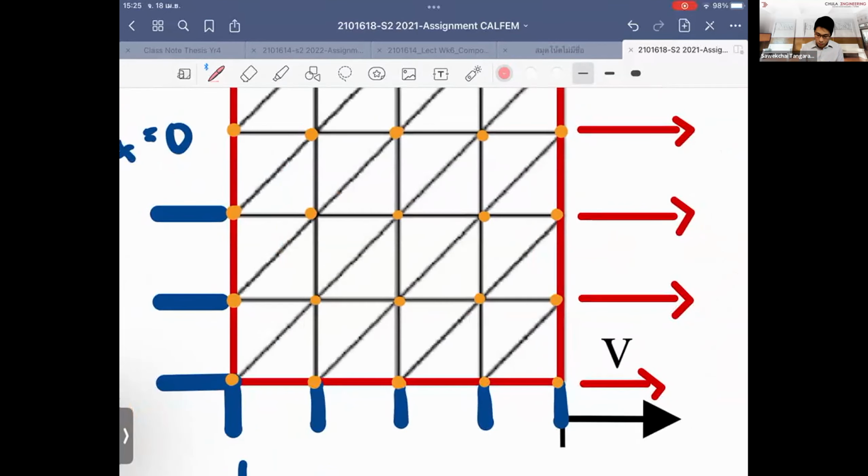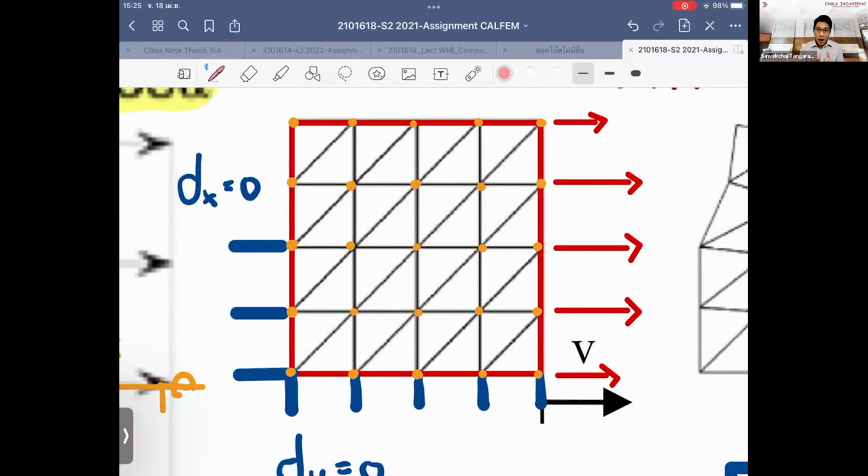So you start from the mesh, and the only thing it cares about is how you orientate the order of the nodes in the element. The direction that you start at the start node, and you keep rotating the node to form the rectangle elements, you should follow the same order for all the mesh you're looking at in the problem, right?